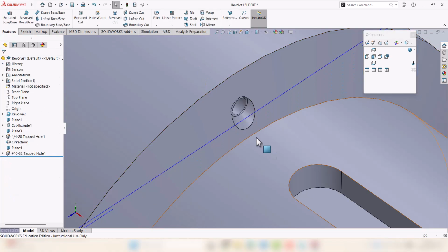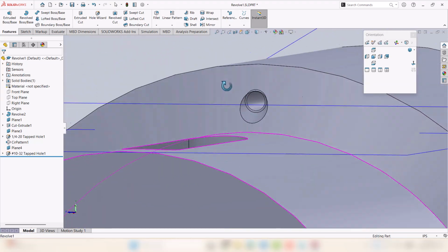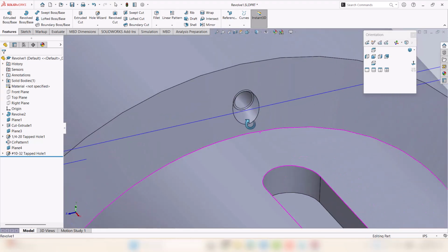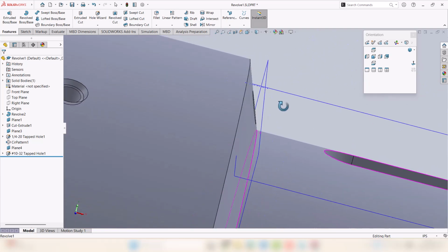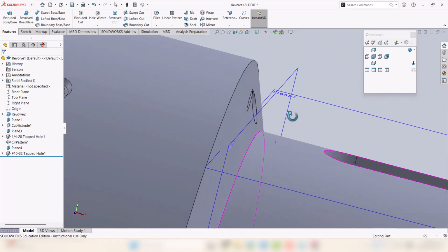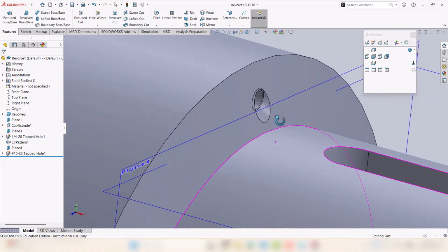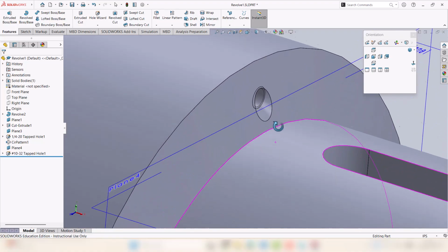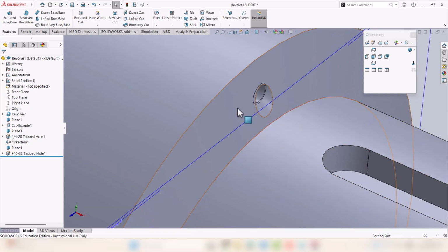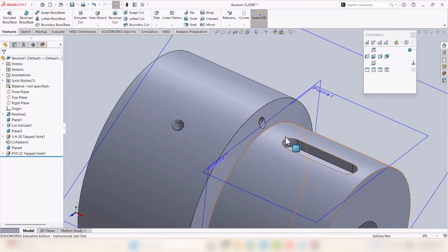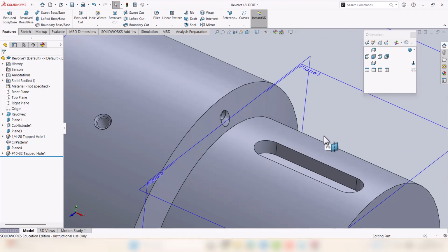Okay, so now we have the chamfer all around, kind of, right? Again, it's because of the amount of angle. The angle is substantial. That's why the chamfer is way bigger on one side and smaller on the other. But yeah, by changing the depth of the plane and by increasing or decreasing the diameter of the chamfer, we can kind of achieve what we wanted to achieve.